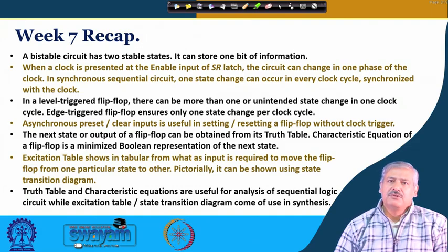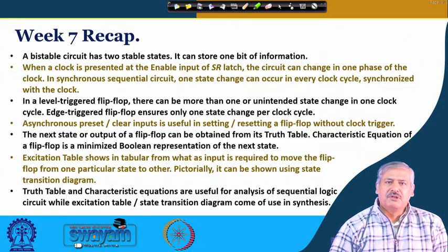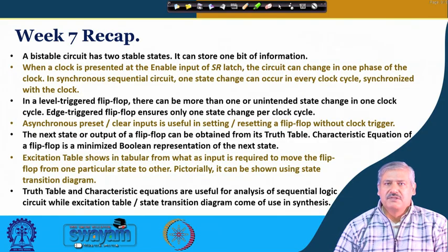And we also studied asynchronous preset and clear input, how it performs and how it changes the output or the state without requirement of a clock trigger, and which is useful for initialization and various kinds of resetting purposes.